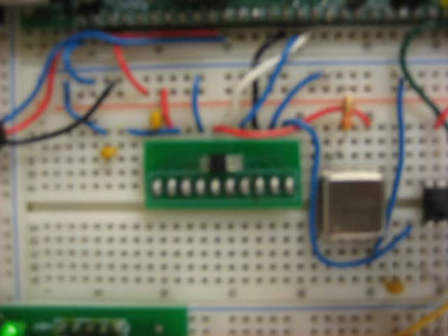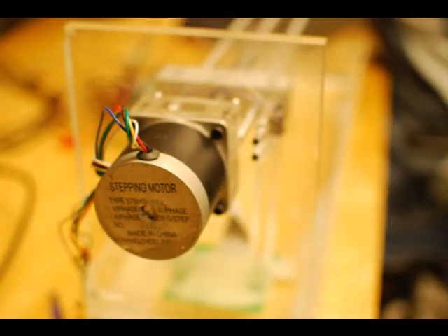In order to generate the emitter waves at discrete frequencies from the PIC, we use an AD9833 function generating chip. We are able to send values from the PIC to this chip that correspond to the waves between 100 Hz and 10 kHz we require.